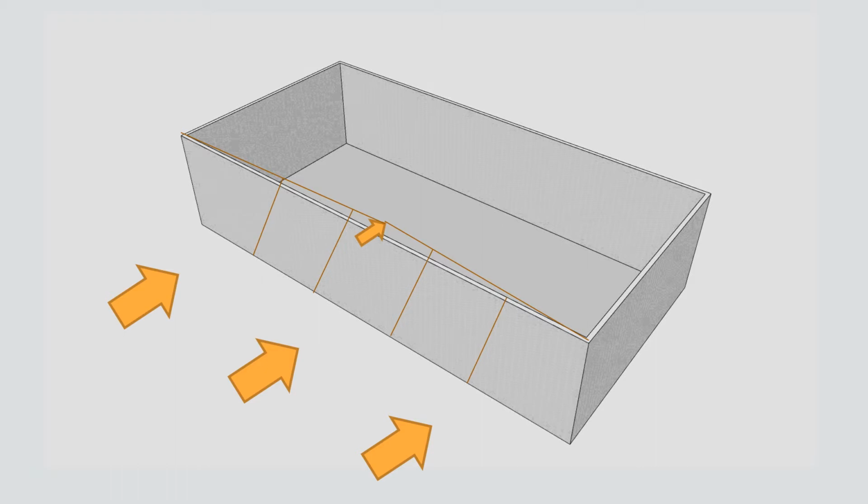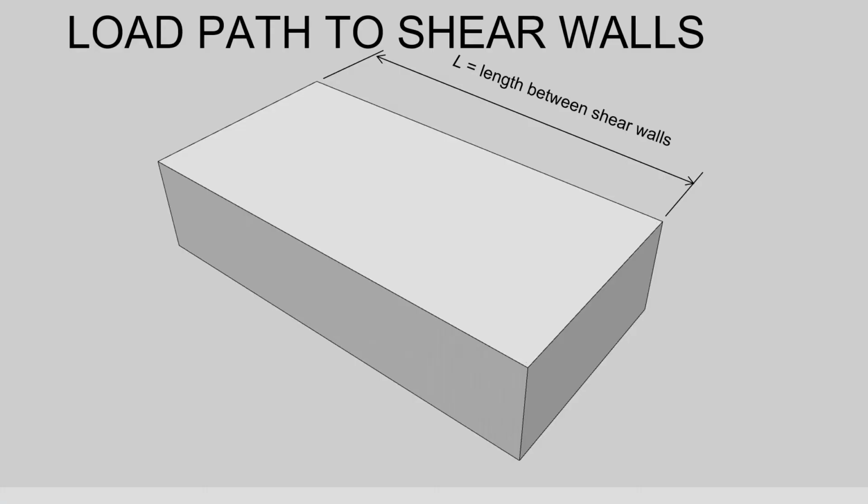While the following examples are based upon a one-story building, the discussion of diaphragm chords applies equally to the floors and roof of multi-story buildings. Here we see the previous building, but now with a roof diaphragm. As the wind or seismic forces impact the building, the walls span vertically, producing a load at the top of each wall as well as the foundations.